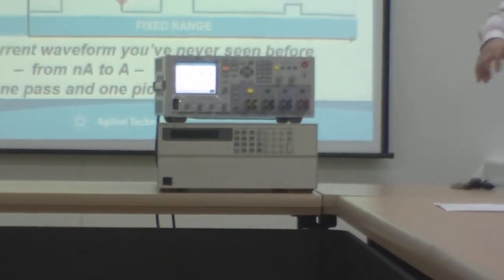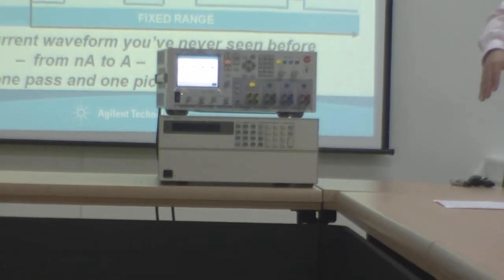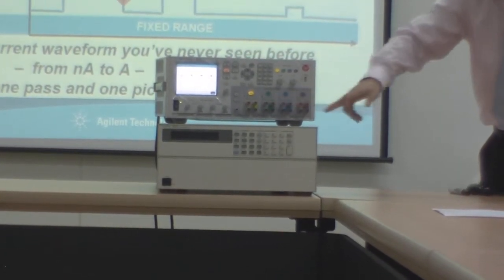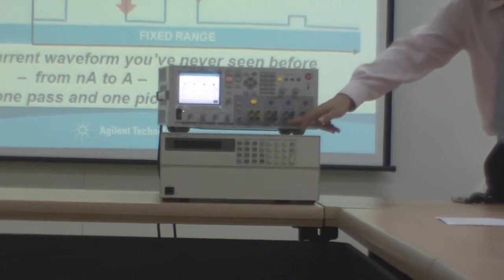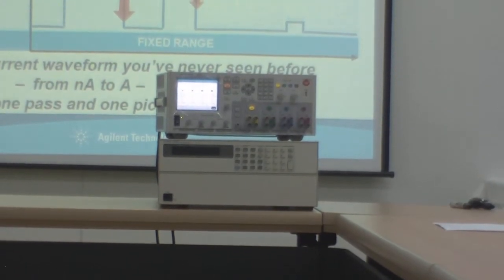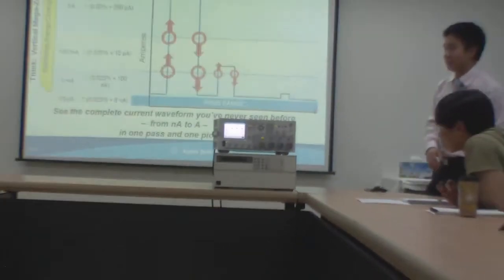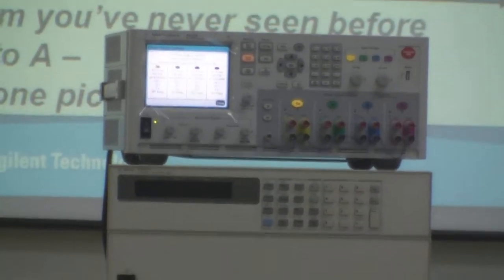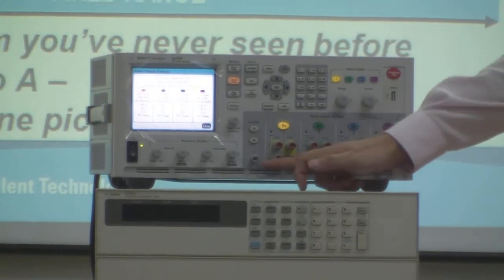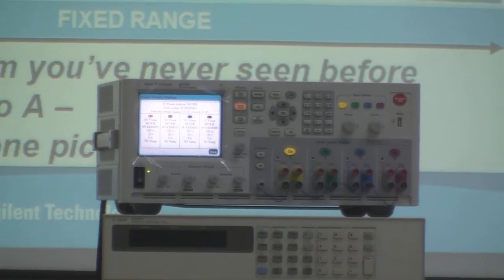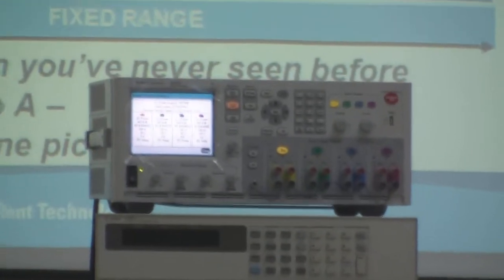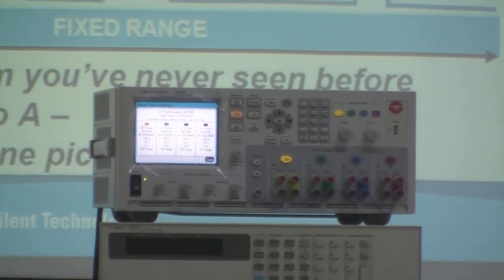So the device will also be connected to the ground terminal? Yeah, so what happens is that internally, their references are all connected internally. So if they did not short this all together, the reference will be made inside their board, which they don't want. They want the reference tied outside, to cut the ground loop. Yeah, ground loop, that's actually the word I was thinking. They want to cut the ground loop. So the device is also connected to that ground. Otherwise, it doesn't have to connect to this ground. Yeah, okay, ground loop. That's what I was looking for, ground current.